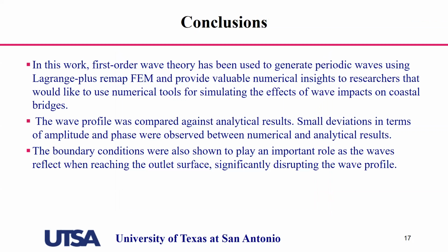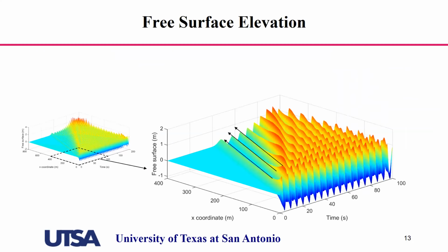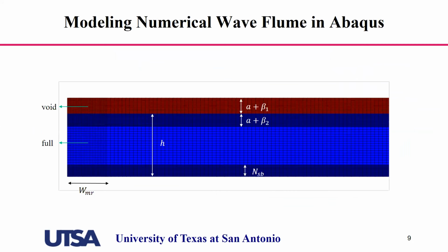Okay, that's a very good point actually. Look at the mesh. This is a very highly dense mesh. It's a bit complicated, but let me break it down. When you simulate only fluid, it allows a very large time step, so you don't need that much time. But when you use structure along with fluid, the structure requires a very small time step. So when I use the superstructure, the simulation can take weeks to compute. For 1 minute of simulation, it may take weeks.